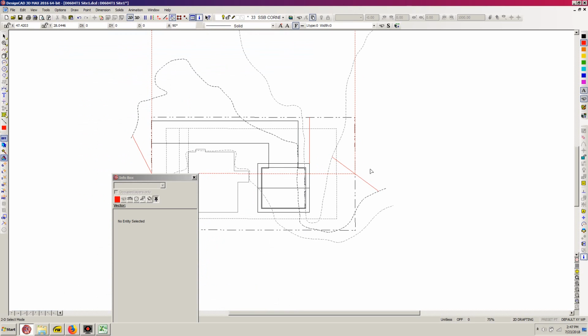So now that we know that we're okay with our solar setbacks for our upper floor project, we'll be in our next lesson dealing with some of the additional realities of the project, having to decide, for example, which way we're going to run our floor joists. On one hand, if we run them the short distance, which is usually the norm, those floor joists are going to be adding to the loads over that garage door header. So we might want to see if we can run those joists along the east-west direction to keep from imposing any huge additional loads on that existing garage door header. So we'll be taking a look at that and a few other things in our next lesson.